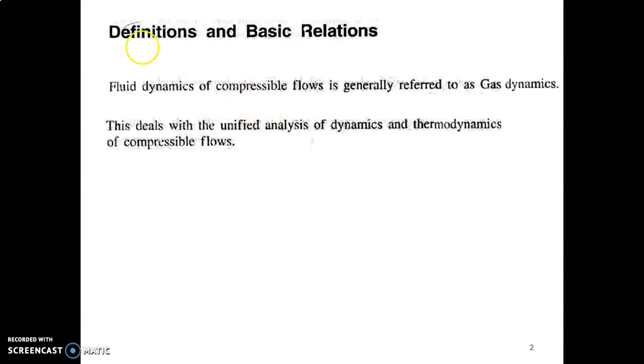But when we are dealing with compressible flows, we will be dealing with gas flows and density-varying flows. In this case, we need to study the thermodynamics of the flow also. That is the main difference between incompressible and compressible flows. So we can also say that is the main difference between fluid mechanics and gas dynamics.